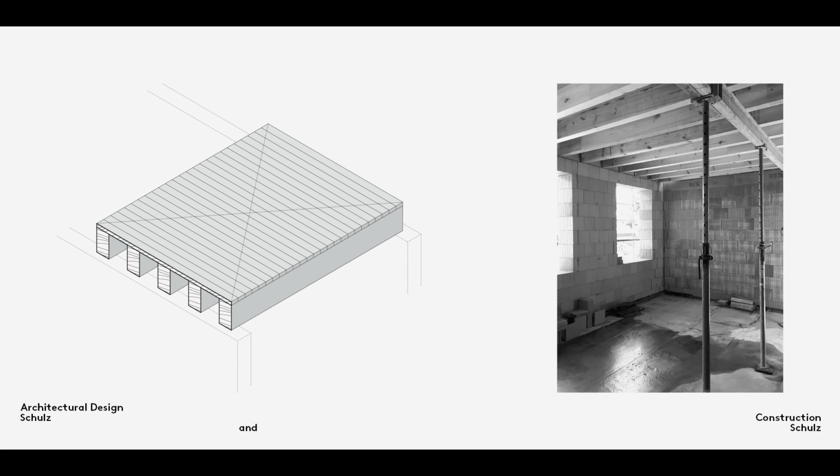Hopefully you will remember that a floor is able to transfer horizontal loads if it acts as a rigid plate. If timber joist ceilings are to have this property, the decking laid over the beams must exhibit this plate effect. This happens when the individual boards are connected together or continuous flat steel strips bands are placed diagonally on top of them. This plate effect can also be achieved more simply by the use of large format wood composite sheets, though this will alter the appearance of the ceiling below.